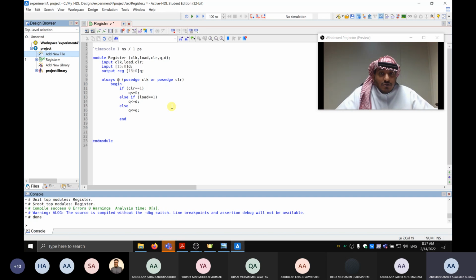In Verilog, you can assign some variable for encoding only, not like in the actual system or the actual module. I want to name a variable and then use that variable as the sizes or maybe other things. So let's say here I will make a variable called n minus 1. If n is 16-bit, n minus 1 will be 15, so it's the same thing. And then I will make this n minus 1 instead of 15.